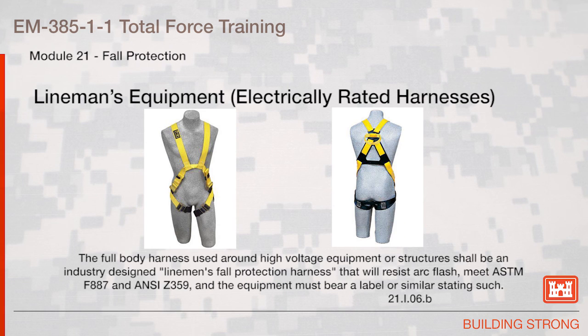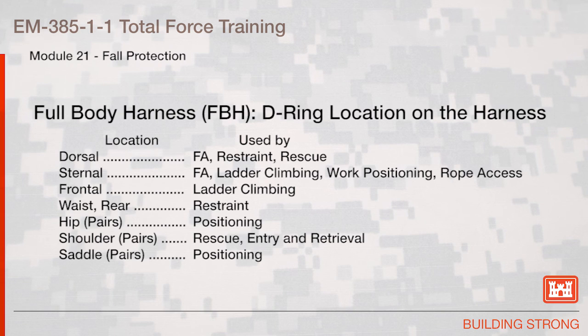Lineman's equipment or electrically rated harnesses. The full body harness used around high voltage equipment or structures shall be an industry designed lineman's fall protection harness that will resist arc flash and shall meet ASTM F887 and ANSI Z359, and the equipment must bear a label or similar stating such.